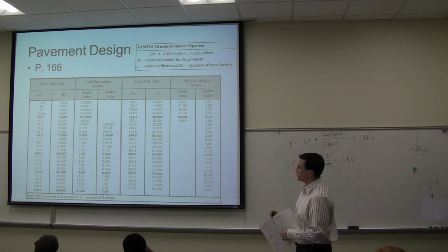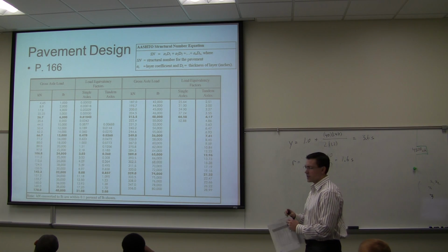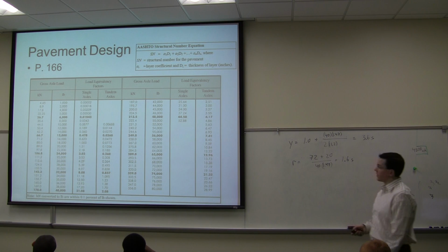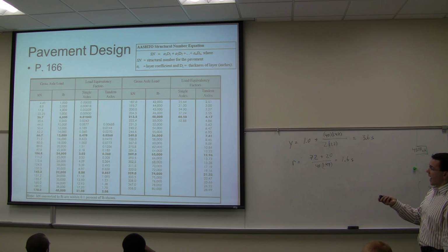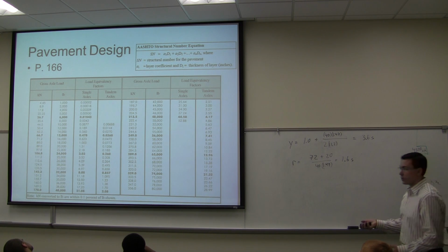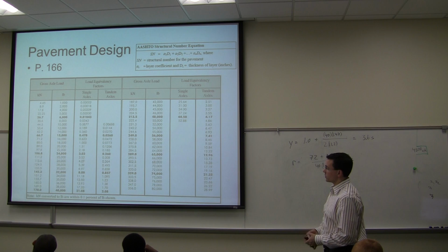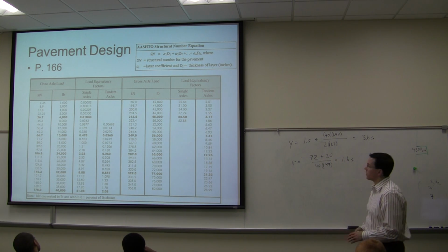This is essentially the same thing as an ESAL, which was one that was in transportation class. So for an axle of a given weight, number of pounds, how much damage is it doing to the pavement? That's essentially what we're calculating.